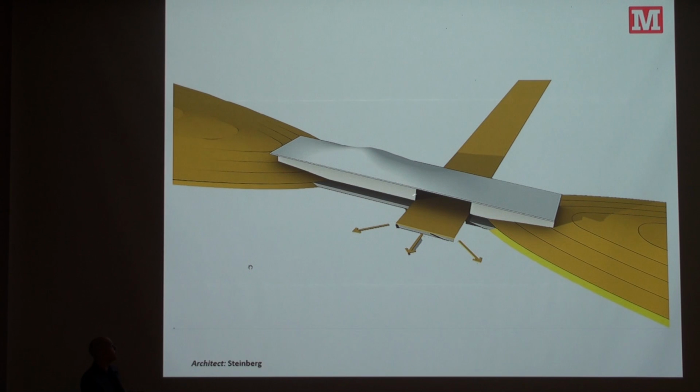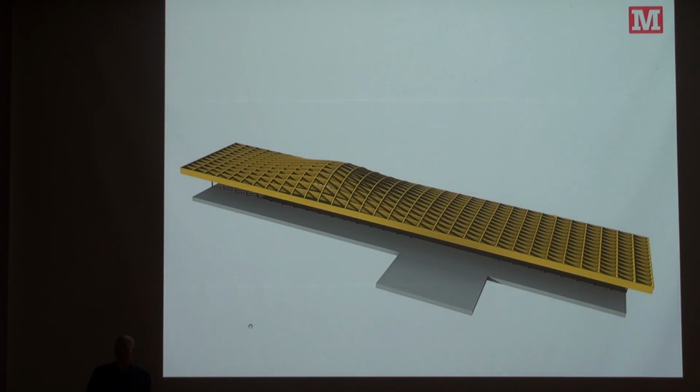And so this building needed to really manage how it sits in the site and be responsive and actually take the landform. And so this has a green roof and all of these things on it. And so I'm coming up with a structural form that is highly integrated, like the puzzle pieces. So these are glulam ribs and purlins all tied together.